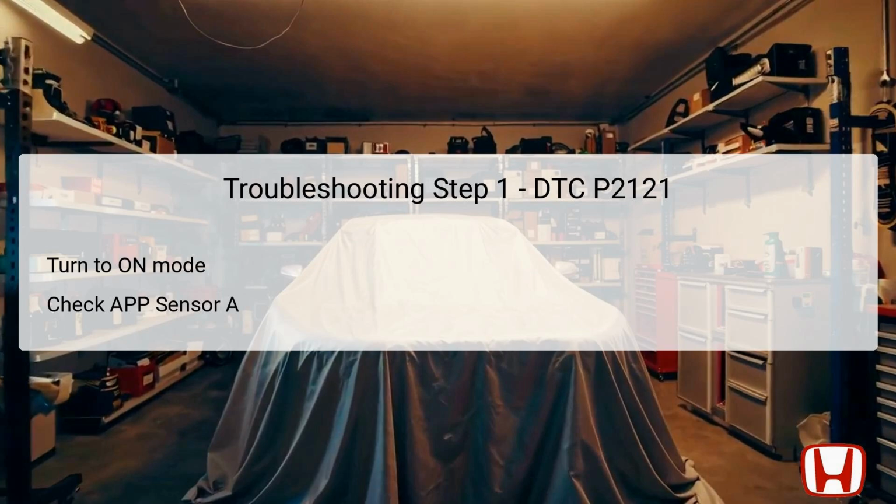It should be less than 0.69 volts. The threshold values are critical. If the measured value is less than this threshold, you may have duplicated the fault condition and can proceed to step 3. However, if the voltage reading does not match, move on to step 2 for further diagnostics to determine the next steps to take.